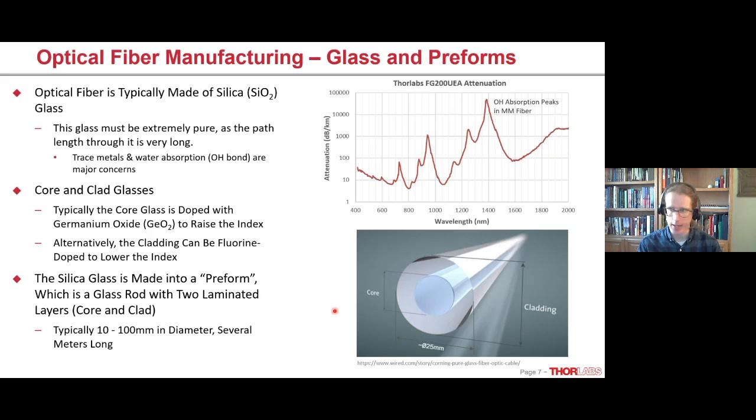That was one of the examples I had on my fiber devices slide. This will split out all these different wavelengths in very small windows, 1550, 1550.1, 1550.2, or maybe even finer, probably actually a lot finer. In that way, we can transmit multiple signals through one fiber at the same time. I know there are also some different strategies with the polarization state of the signal that goes in.